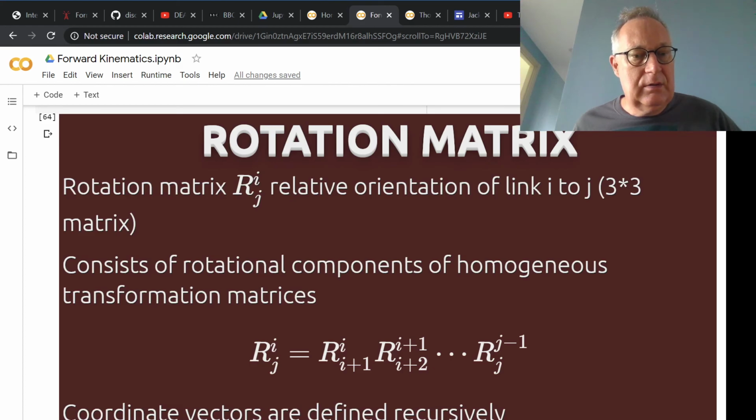So the important thing to realize is that the rotation is important. Our displacement of the origins is not all given in the world coordinate system, but actually in the local coordinate system, which is why when I add them up, I need to look at the current alignment between link I and J minus 1, and then apply the transformation matrix.